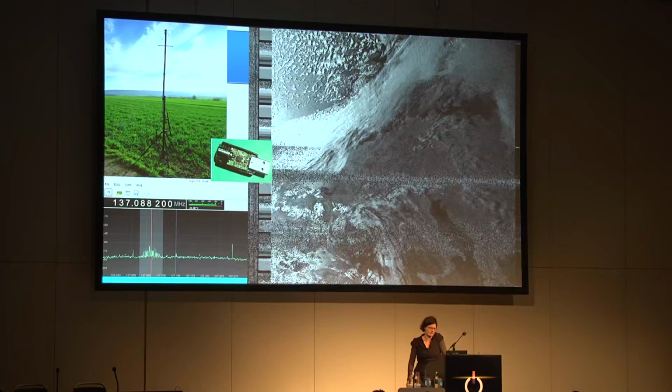you lose something. It also depends on whether you are indoor or outdoor, because every reflection and all the scattering also manipulates your signal, so you don't only have a vertical component. But often it makes sense to move the antenna a bit if you have a bad signal, or in much modern equipment you have two receiving antennas that do some kind of receiver diversity to get both components of a signal.